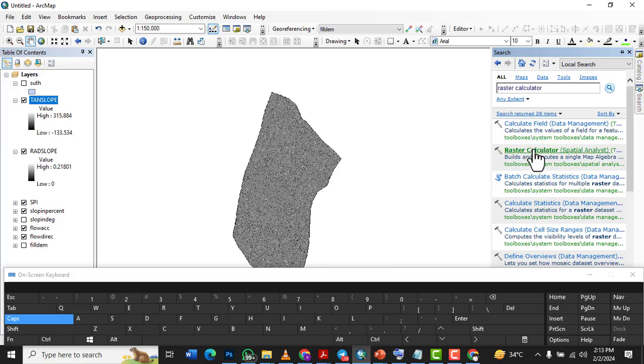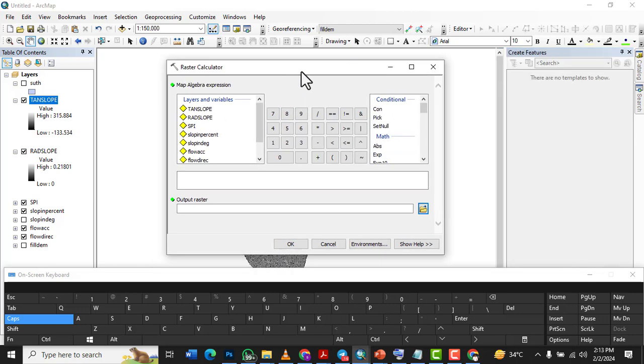So we still need the raster calculator. To calculate the flow accumulation scaled, we're still going to punch some formulas again. So we're going to say flow accumulation plus 1. Then you close the bracket. I'm supposed to open the bracket first, then close the bracket.